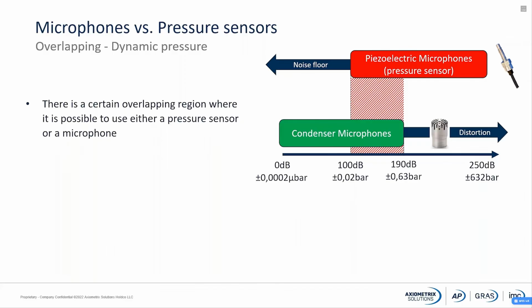Nothing is really static in this world, but at least it is stable for some time. So if you take a sensor that is comparing the pressure with the atmospheric pressure, you can, for example, take the example of measuring the pressure in your car tires. There you put on a measurement device and you can see what is the pressure in your car tire, and you compare it with the ambient pressure, which means the atmospheric pressure. That is very much a static pressure because you don't have any fluctuations in the tire, and therefore it is a static measurement.